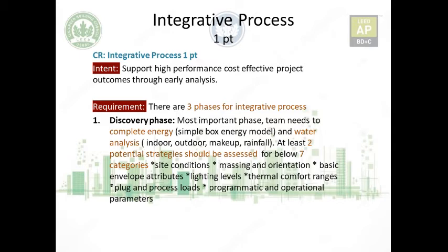In this phase, the team needs to complete energy and water analysis. The energy analysis could be a simple box energy model through software which is available online. And for the water analysis, you should consider indoor water, outdoor water, makeup water, and the water through rainfall should also be considered. And then you have to assess at least 2 potential strategies for the below 7 categories, like site